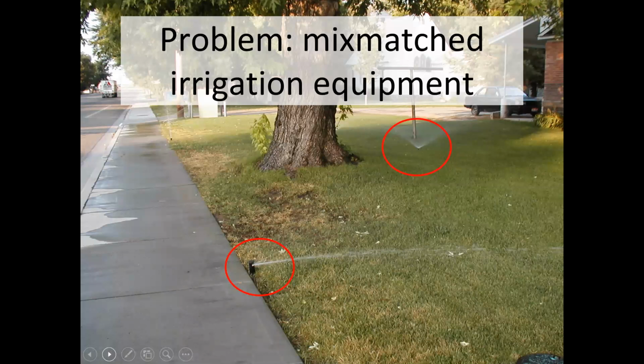The next issue that you could encounter is mismatched irrigation equipment on the same zone. As you can see in this photo, we have a rotor on the same zone as a sprinkler, and they have different pressure and throw rates. So they're competing with each other, and that's causing some runoff, as well as some areas that are under irrigated and over irrigated. So this is a difficult zone to manage.